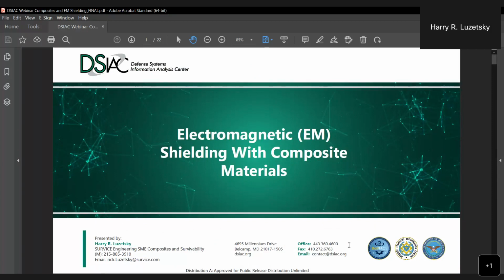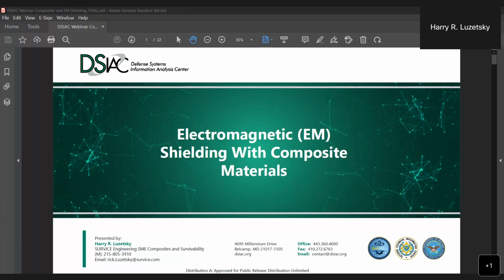But I can comment on the two ways that we actually have measured, both of which are acceptable per ASTM standards. One is you take a box, and within the box you place your antenna. The box itself is sitting in an anechoic chamber, and you have receiver antennas outside, measuring the radiation that is escaping. The other system we used is an anechoic chamber that has a hole cut in the side with a mounting fixture, and we put the panel there. We have one antenna outside and one inside of the anechoic chamber, so you're looking at the transmission essentially through that window.